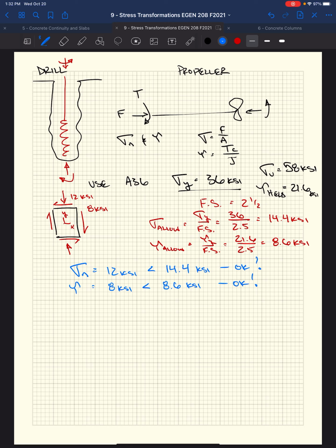This isn't the end though, right? We gotta check our max stresses, right? And as we've been going through Mohr's circle, there's a good chance that even though we found this initial stress state based on our imposed loading, the combination of our shear stress and normal stresses will result in principal stresses and maximum shear stresses at a plane that's not oriented within the axis of the shaft, right?